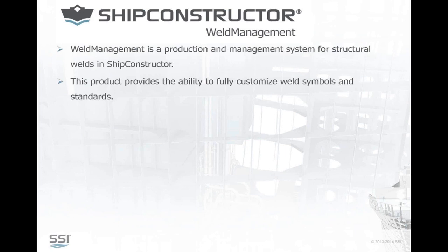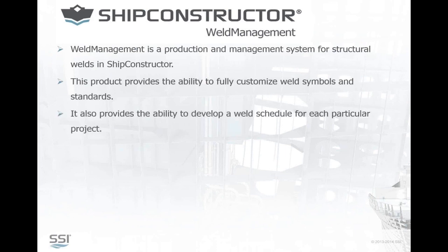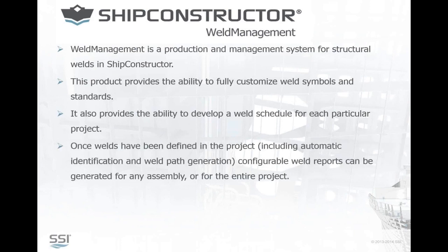So WeldManagement is a production and management system for structural welds in ShipConstructor. Now this product provides the ability to fully customize weld symbols and standards, and we'll see some of that today. It'll also provide the ability to develop a weld schedule for each particular project. Once welds have been defined in the project, including automatic identification and weld path generation, configurable weld reports can be generated for any assembly or for the entire project. So a lot of reporting capability built into the product.